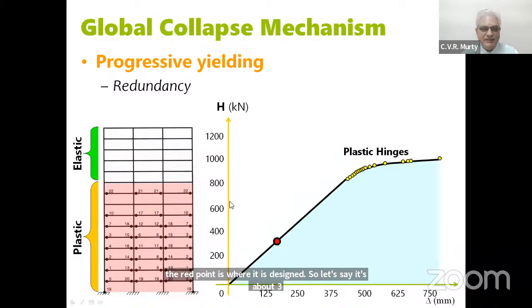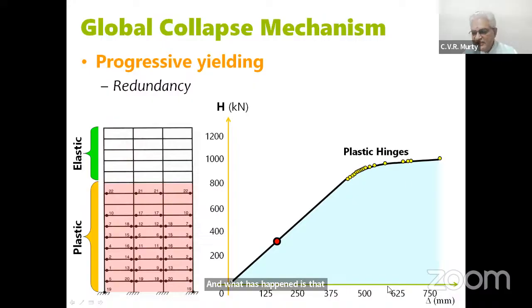And what has happened is that the structure, when it is going to the extreme displacement loading, will follow the actual capacity of the structure. And that value is coming to about 950 or so. So 950 by 375, approximately a little less than 3, is what I am talking about as the ratio, 2.5 that we are giving in the structures.